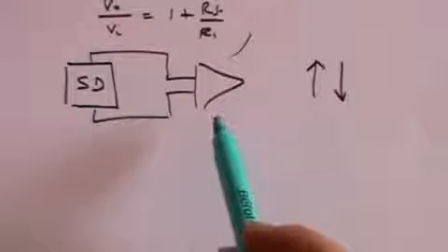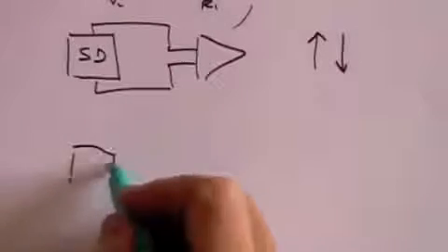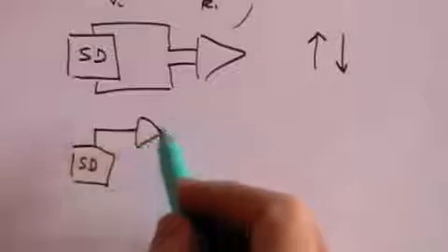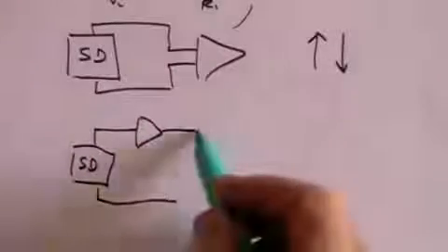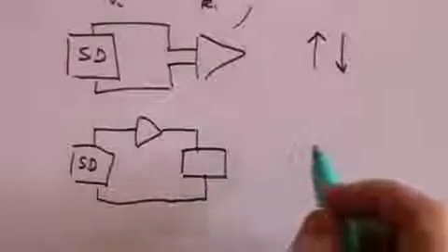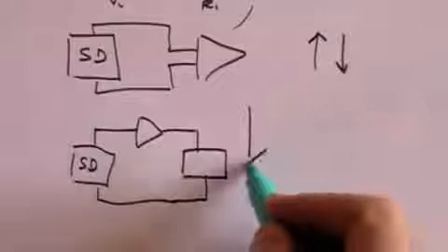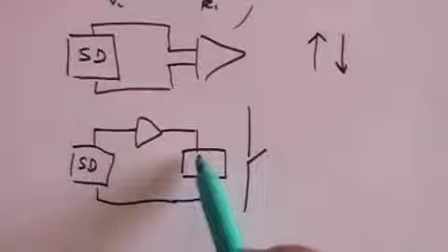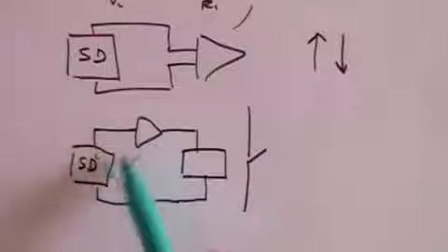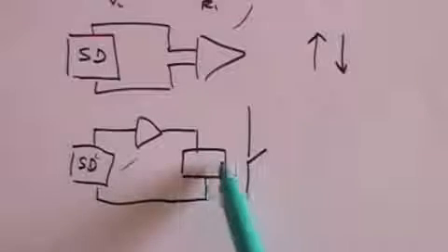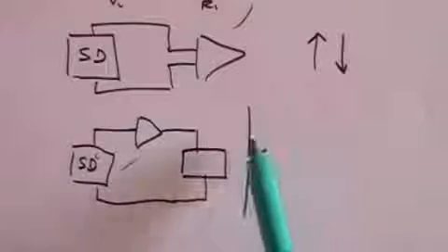And so we have to use what's called relays. What that means is that the circuit of which the sensing device and indeed the operational amplifier is a part will come to some kind of device here that will cause a switch over here to switch on. So somehow the action of the sensing device and the operational amplifier will cause this, whatever this is, to make that switch close.